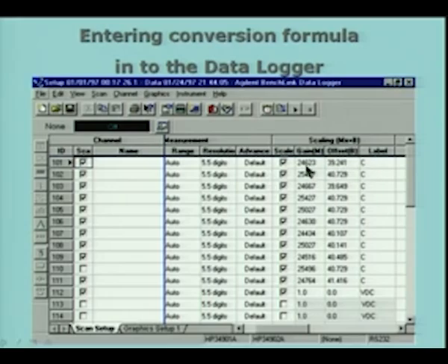So, the temperature automatically is going to be recorded by using this particular formula. For each channel I can have a different formula, or it may be the same if they all have the same constants or coefficients given here. So, I can convert the input to each channel in terms of voltage to degree Celsius, and that can be done here.